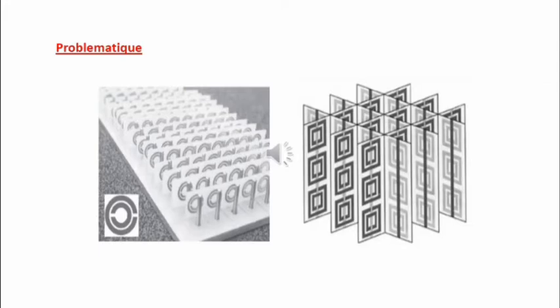These metamaterials are often periodic structures, dielectric or metallic, with a very small period in front of the excitation wavelength, and which behave as homogeneous materials, therefore can be described by so-called effective parameters such as permeability and permittivity, and do not exist in the natural state.